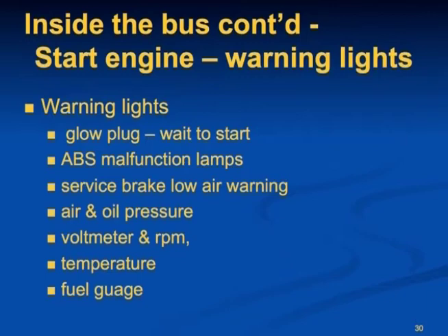Continuing on with your panel, the service brake low air warning light should come on when the air pressure goes down to about 60 psi. Pull off the road to a safe location and call for assistance if that happens while you're on the road. Do not drive the bus unless you have at least 100 to 125 psi.